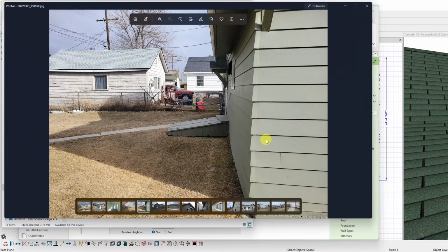And this takes you down into, maybe we'll get to a point where I'll take you down inside, show you the problems. There is actually a video that shows the problems where, because of the soils we have in this area, which is decomposed granite, it's just concaving, and the wall that runs through the house that's bearing is undermined because of the dirt that's disappeared.